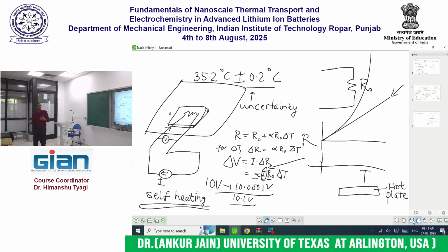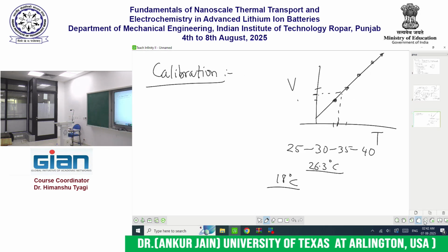But at the very least, you should do step number 1, which is that you have a good quality hot plate, perhaps brand new, from a good manufacturer, and you trust it, right? You carry out your calibration at multiple temperatures on that hot plate. And then you have this calibration chart, which can be used for good accurate measurement of temperature. Does that make sense? Any questions?